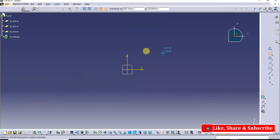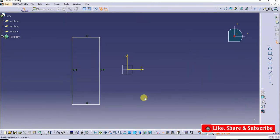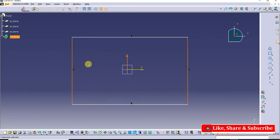Now let us consider another case here. I'll select the rectangle command. Now see what will happen here. Press the Control key on the keyboard, select this, and second this, and third this. See here, now the sketch is moving away from this. So in order to prevent that, you need to select the lines first, and last should be the axis line. See here, now the sketch is not moving away from the axis.